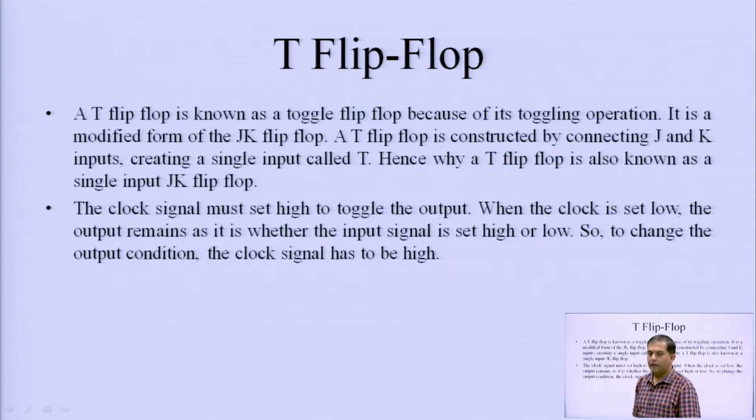Now, the last topic of today's class, the T flip flop. T is the toggle flip flop, because it performs a toggling operation. We have already discussed the JK flip flop, and here the same input is connected to both the J and K inputs. This is the working principle of the T flip flop.